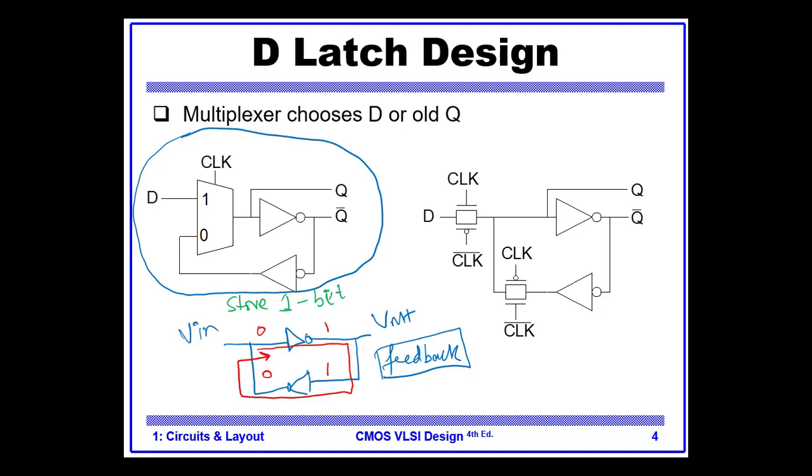So what happens is, if the clock is 1, then the multiplexer selects this input, and the bit goes to Q and Q bar, but Q bar is connected here, so it goes here. But this path is closed because clock is 1. So we say that the D-Latch is transparent.